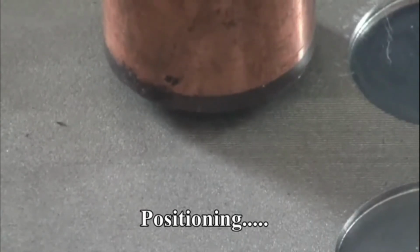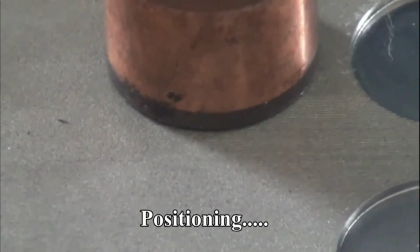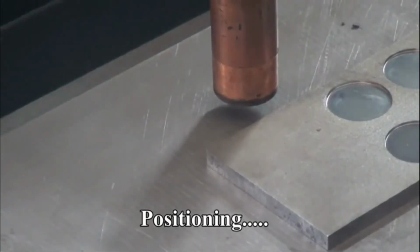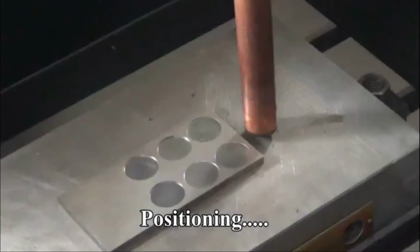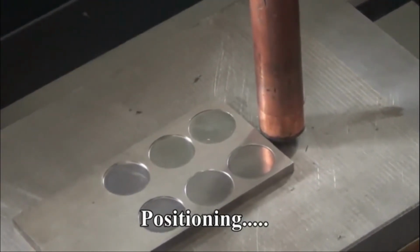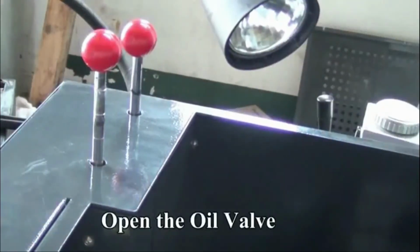Next, before starting the machining, positioning is very important, because this is where we want to machine, where we want to remove the material from the surface. That position is very important. Under positioning we want to maintain the electrode gap between the workpiece and the electrode, because that parameter or factor plays a very important role in the EDM machining process. For that reason, positioning is a very important factor. In positioning, we are maintaining the gap between the electrode and the workpiece.